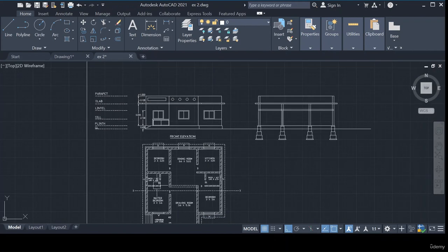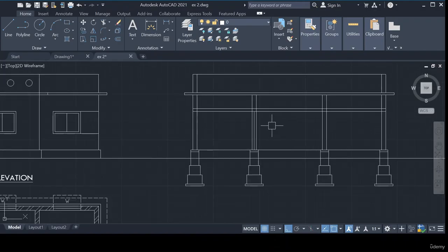So this is our wall. From here I just take the offset 1.05 from the right corner, from this wall and from this wall. And what is the height of the window? That is 1.2 meters. The remaining part I just trim.